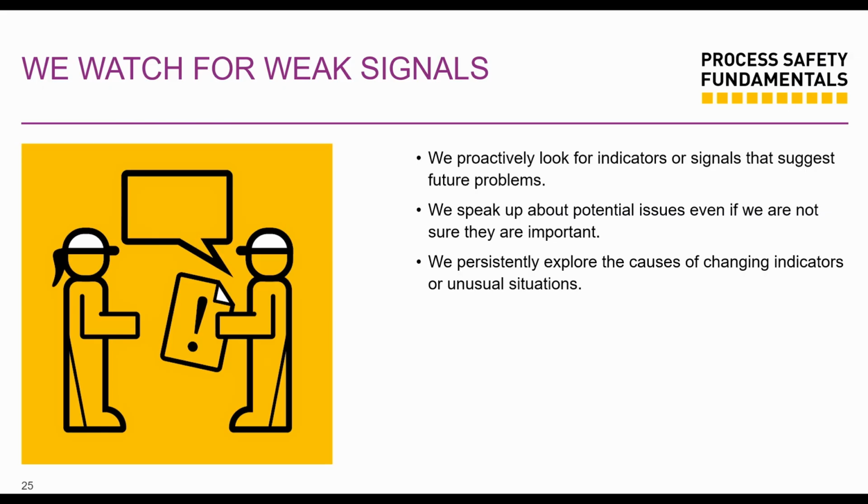Instead of accepting it as normal, that, hey, in 10 minutes this is gonna stop, no, it's not normal. Check the root cause. It might be a shaft that's misaligned or a seal that's failing. And before that seal fails catastrophically, because it could do that 10, 20 times over the course of 2 years, and then eventually it fails catastrophically.